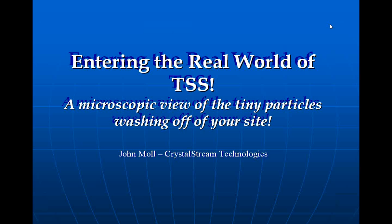Quite often the effort is to minimize flows, use the lowest range of curve numbers or C factors to make a pond smaller, but the proper design percentage and the size of the BMP really does make a difference. And if you're looking at water quality, it can be a critical factor.